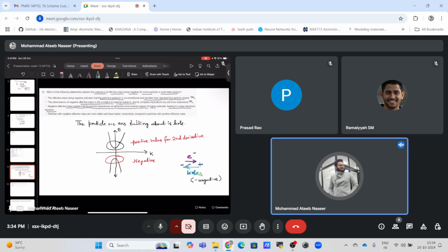An energy band diagram means the variation of energy with x, that is, the position along the device, say the channel length. But an energy band structure is drawn with respect to the reciprocal lattice vector, so it is in the reciprocal space.